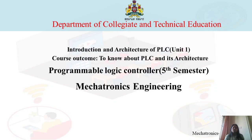Then after that, we have seen what are the major components of PLC. The major components of PLCs are the CPU. In the CPU, we have the microprocessor, memory unit, and power supply unit. The microprocessor in the CPU does all arithmetic and logical operations, and it also controls the operations. Then we need the memory to store whatever program you are writing. And then the power supply unit.